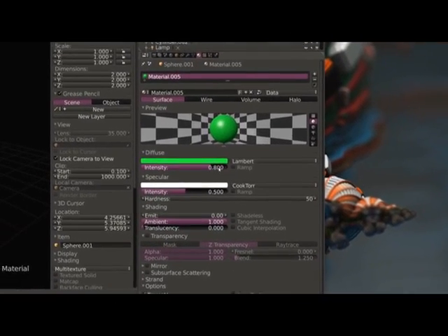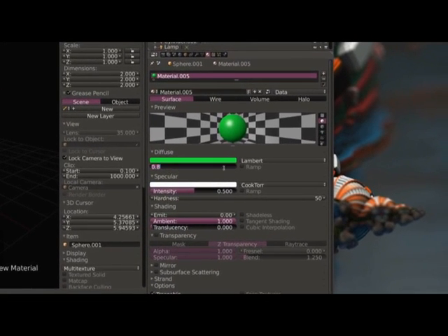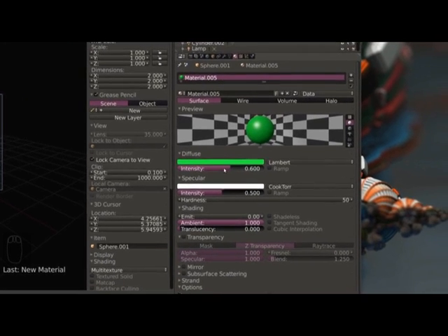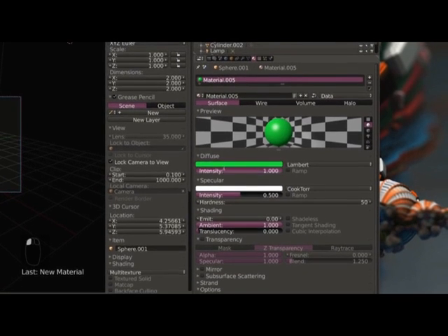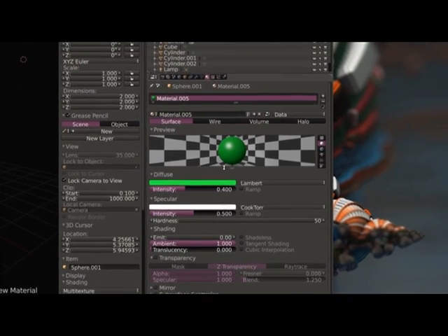And in fact, you can change lots of properties about the color, translucency of your object. You can do a lot of different things with it here if you'd like to. So for right now, I'm giving it a green color, and I'm going to change the intensity to 0.6, which just darkens it up a little bit. Actually, I think I'll darken it up a bit more, make it 0.4. Alright, so you see that just makes it a darker green.